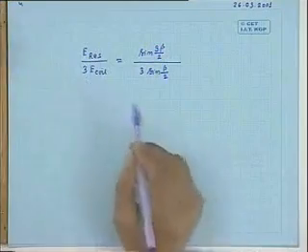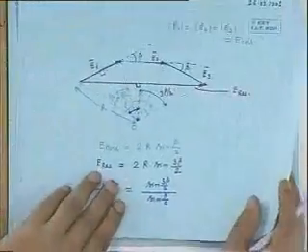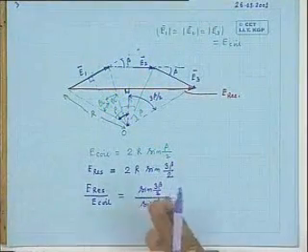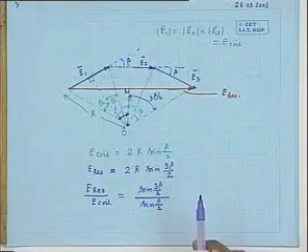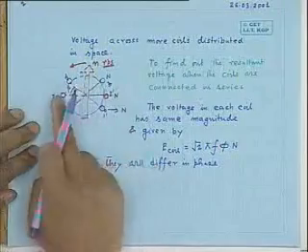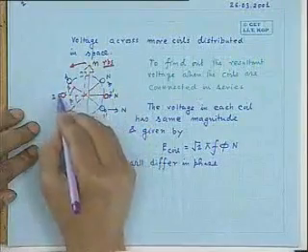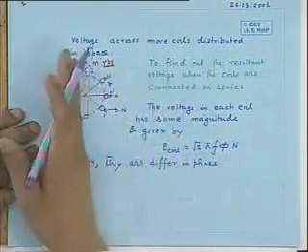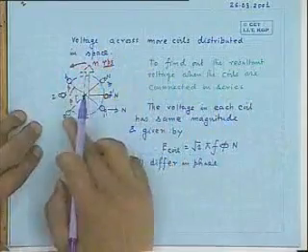Okay. Now the left hand side, let us see, what do you think 3 E coil is? If the coils were not distributed in space, if they are placed in the same place, you have got 3 separate multi-turn coils. Each one of them has n turns. Here I have placed one coil like this, one coil like this, with multiple turns in the same place. The second coil also may have several turns, the same number of turns. And here also another coil, but they are distributed in space.